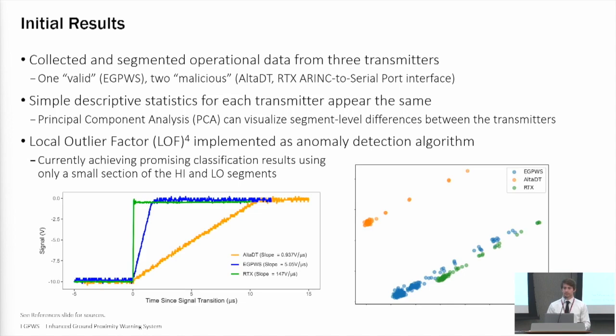Since it is segmented by the one transmitter, 20 receivers, how vulnerable are systems on ARINC 429 to other attack pathways? Like 1553, since it ties the whole aircraft together, you can use a maintenance loader or any number of other ways to get to a fairly critical system. Other than the stay-behind device, how vulnerable would 429 be to some other attack path?